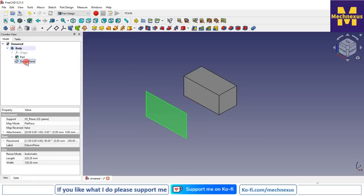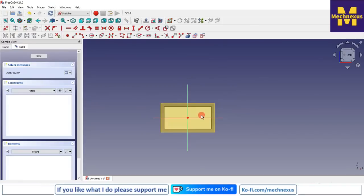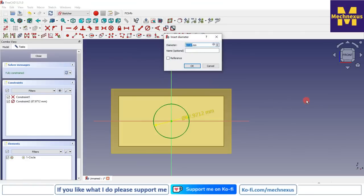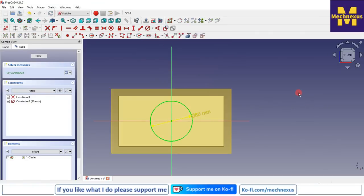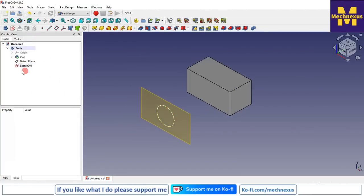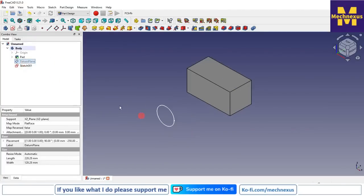Now I will create a sketch on my datum plane. So select the datum plane and click on the sketch, and now here I will create a circle and select this circle and give the diameter dimension. Let's say I give it 80 and I close it. Now I will hide my datum plane. Now I will select my circle and click on the pad.